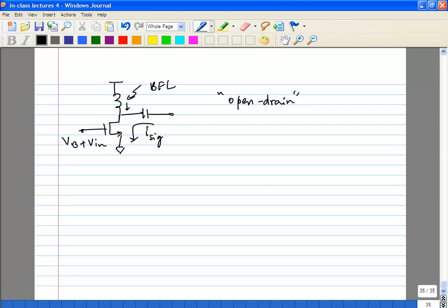If that inductor is very large, the parasitic capacitance, the inside impedance will also not be... You mean here? Oh yeah, definitely, you have to worry about that. So if you're designing for a certain frequency or for an on-chip implementation, then there is a limit on the sizes. Obviously, a larger and larger inductor would seem better, but definitely you're going to have parasitics associated with the inductor, and that is going to steal away some of your signal. So you do have to worry about it. Typically the inductor would be anywhere from, let's say, 7 or 8 nanohenries all the way up to 15 or 16 nanohenries, maybe a little bit larger.